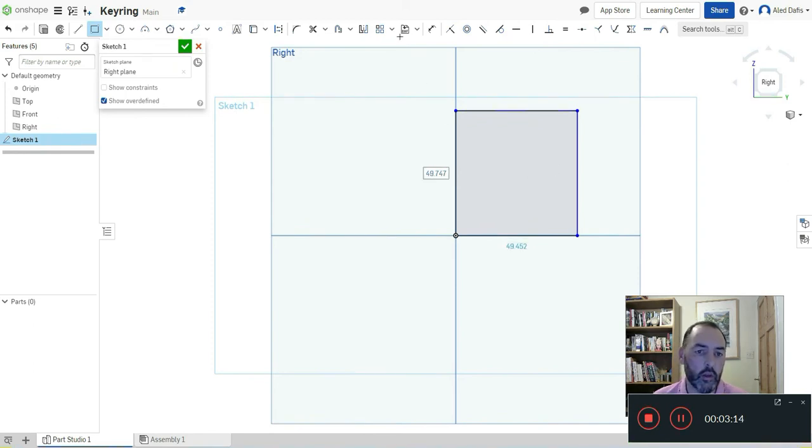So I'm going to pick the dimension tool, click on this edge, drag it up, click, and I'm going to give that a dimension of, yes, 50 millimeters. If you find that these are showing in inches, I've got another little video, just a 1 minute long video on YouTube showing you how to change the dimensions. And once you've changed it once, it'll always work in millimeters then.